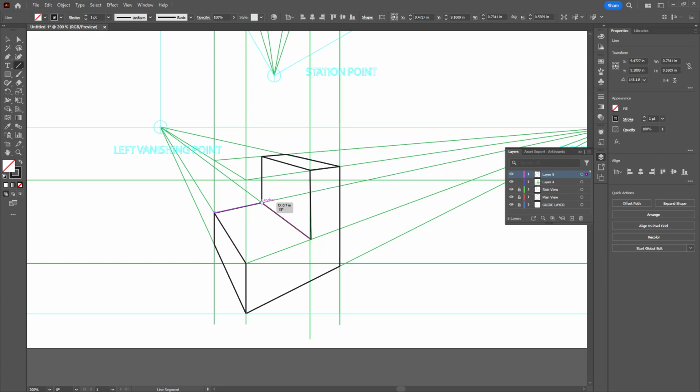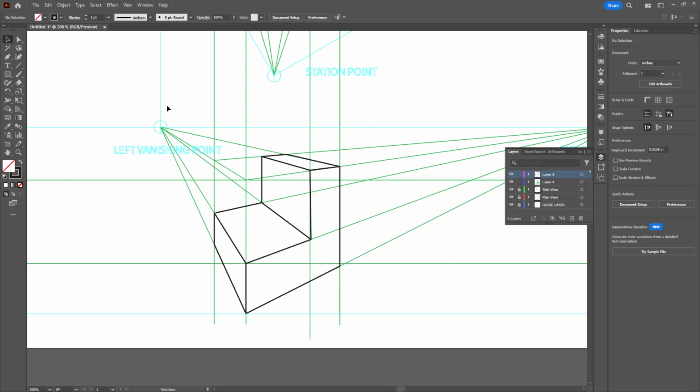And one more here. And now you can see we've drawn that in 2-point perspective. So we've got our vanishing point here, giving us our angle where that recedes, those lines heading to the left and over here to the right. And that is our image.